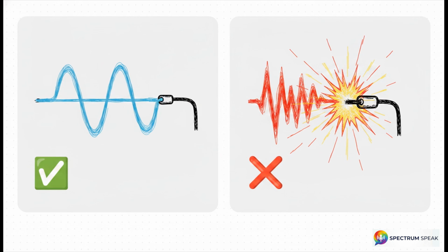So why does this happen? The trap here is largely historical. You'll see veteran engineers often rely on pigtails because, back in the day, or in purely low-frequency audio applications well below 10 kHz, a short pigtail is kind of acceptable. At those low frequencies, the pigtail's inductance doesn't create enough impedance to totally ruin the shield's performance.